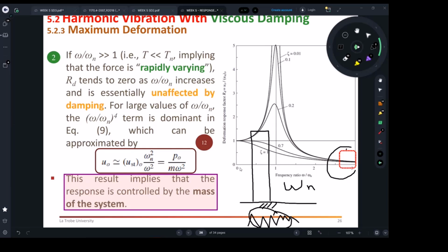Because your building, that's the example I was talking about for the tram. You know, the example for the tram or for the truck. The truck, or the tram, basically, is going to cause a lot of vibration, but the frequency of those vibrations is very high. The building won't be sensing it, won't feel it. Okay.